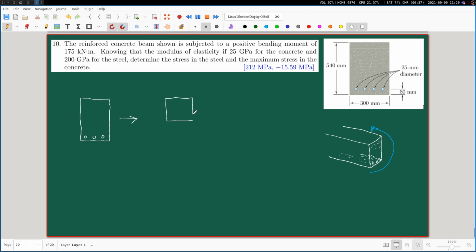So you draw the above part where the compression is taking place only up to that point where the stress becomes zero, meaning to say that this is the neutral axis. And perhaps it will be better if I don't draw it in such a fashion which makes that horizontal line look like the actual original centroidal axis of the cross section. Maybe something different like this. And then you consider the steel rods alone.